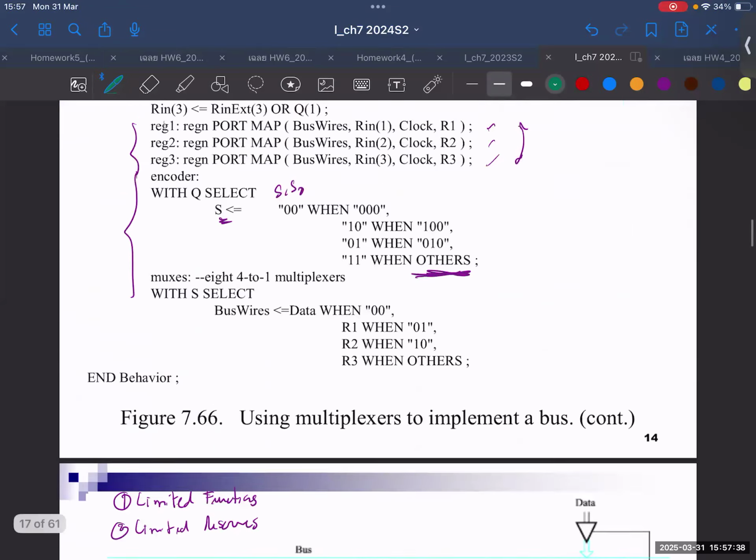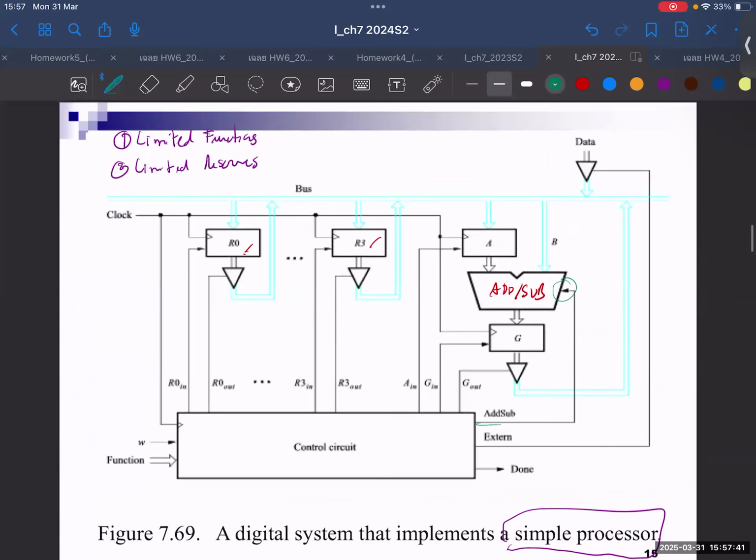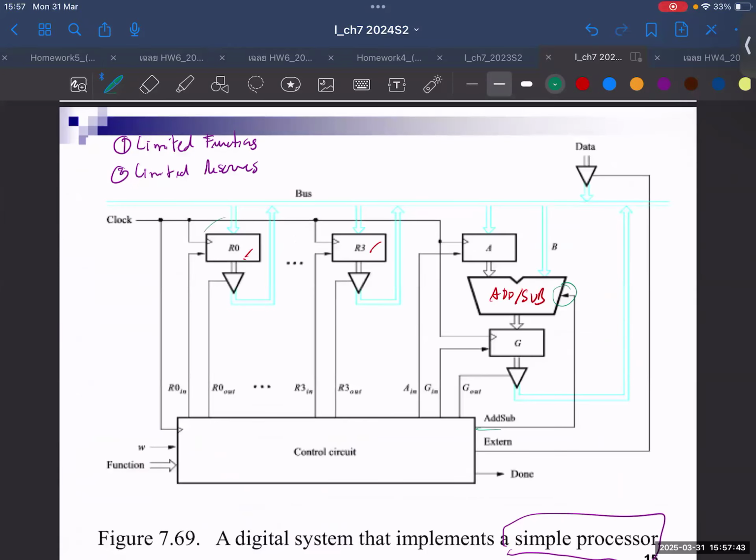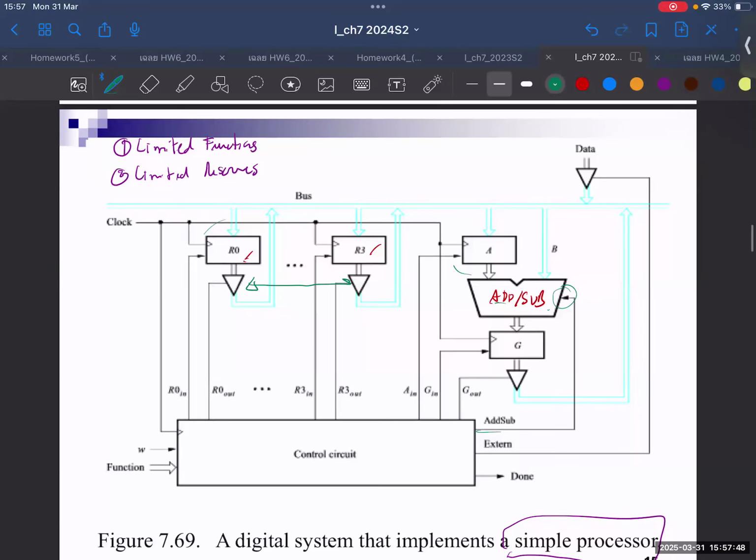Yeah, we run out of time, and of course, except then 3, 4 registers you can work on. You can see that in the add sub, you also need the extra ones we call A and G, and these are not what we call the universal registers. These are universal registers. Why is that? It's storage that can be used by anyone, right? By anyone. But A and G is only for what? For the ALU. This is the ALU, right? For the add sub units.